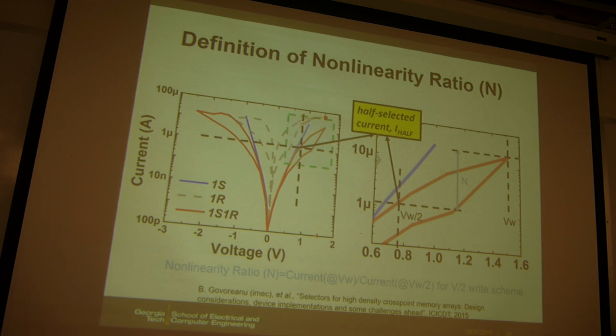If you do nothing, on this dashed line, because it's a resistor, you only decrease the current by 2 times if it's a pure linear resistor. You only have current reduction by 2 times, from here to here. This is on a log scale, so a linear relation actually appears bent. So you only reduce by 2x.